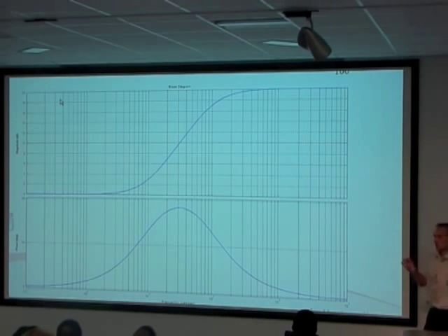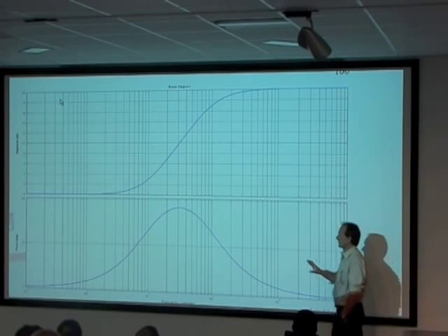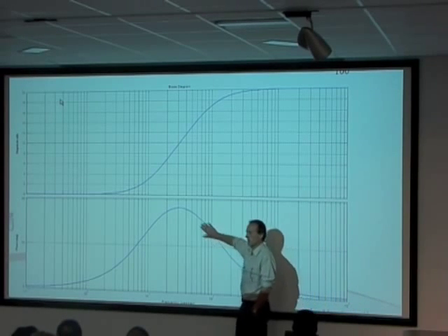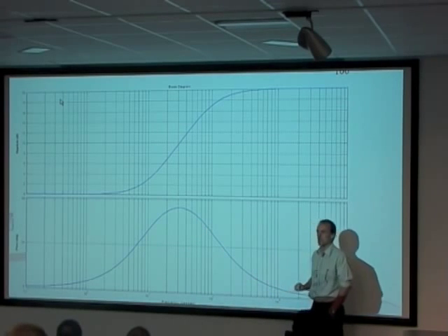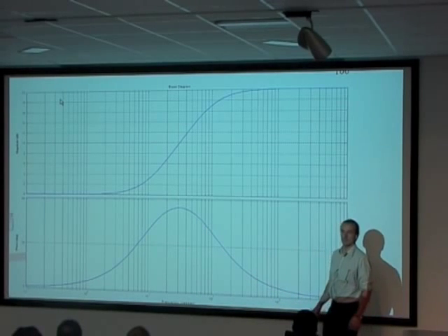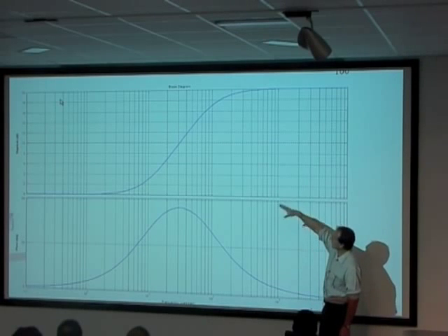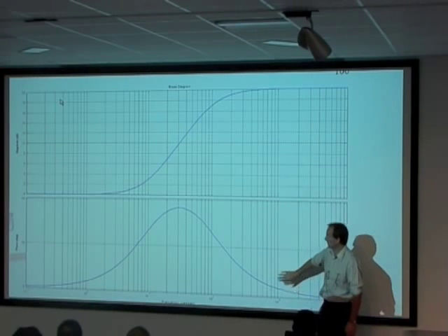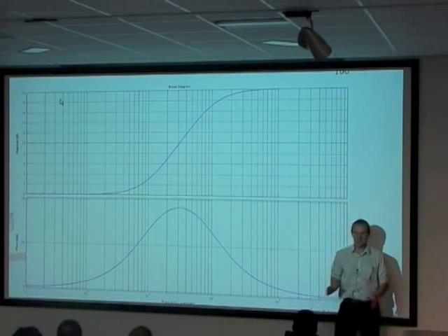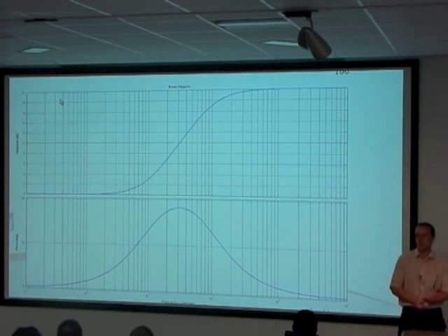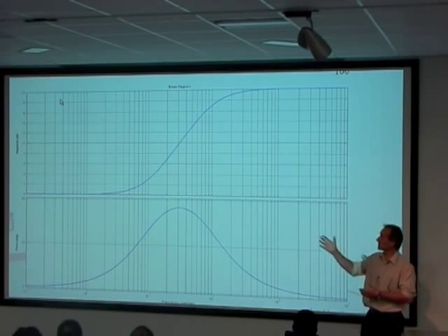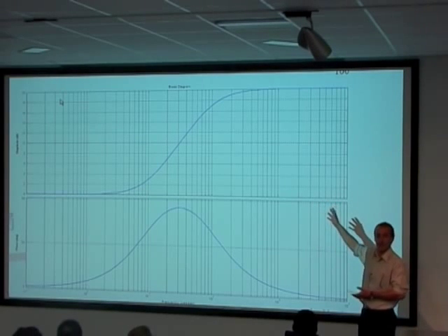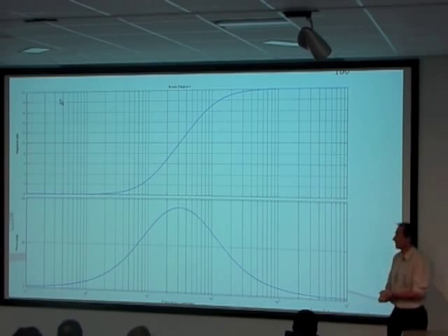Okay, so what this gives us is the ability, and in a sense the phase is the important one, to pop in a quick lump of phase advance where we need it. There is an effect on the overall gain, but we can do some interesting things just by introducing that phase advance. Does that make sense? You can see how this is built up from a lead followed by a lag, and that's a lead compensator.